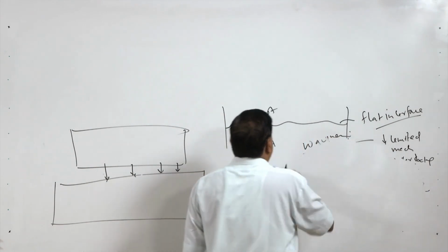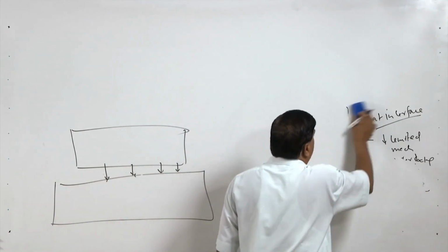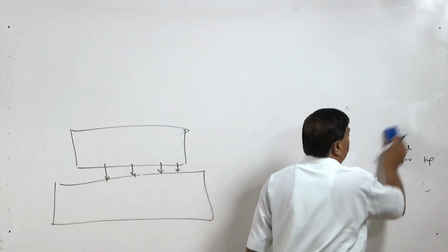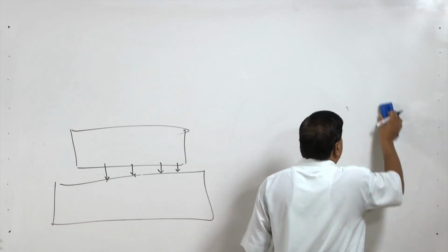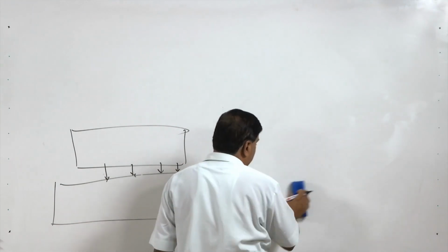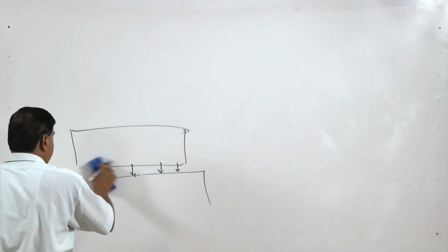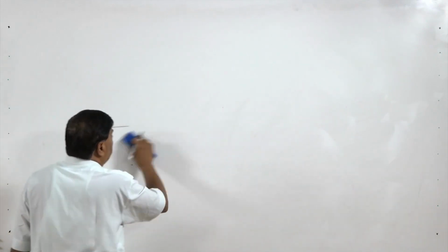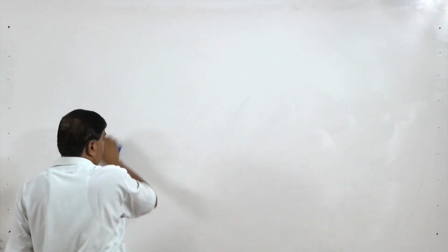Otherwise, the waviness of the interface will be very limited and a flat interface will be formed, which will limit the strength of the bond, and the joint will tend to break, especially under moderate loading conditions, due to the poor bonding and joint strength.